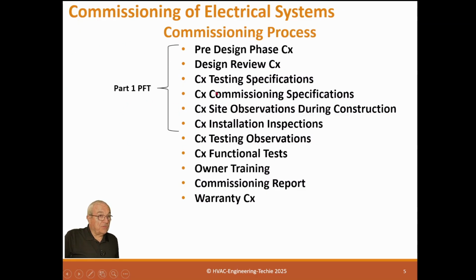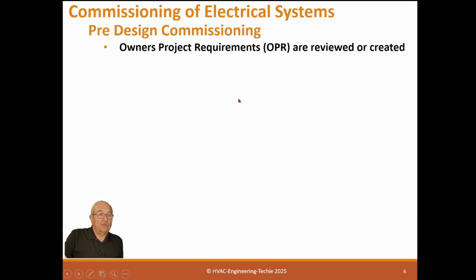And part 1 covers these from pre-design to CX installation inspections, and part of the testing observation. And then part 2 is for this testing and functional test. So right here, these are kind of split between each other. Now, when we get to it, it doesn't really matter whether your test is done up here or down here, just as long as the tests are done. This is just a convenience of being able to describe the commissioning process so you'll fully understand. I'm not sure why, when ASHRAE started all this, they defined PFT, which unfortunately includes 2 different tests, which I'll go over.